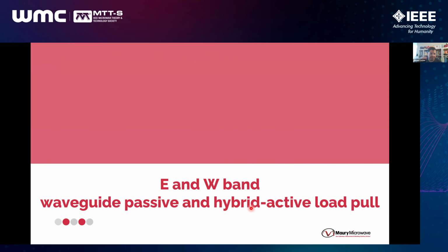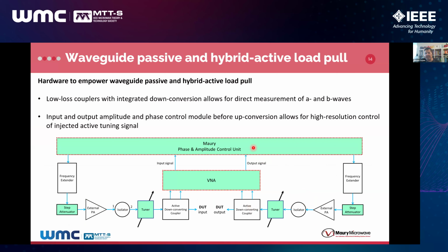And let's switch to E-band hybrid system. So in this case, we use VNA, and the critical difference here, as you know, you cannot control extenders, right? So they are kind of dummy devices. You just inject the power input signal, it multiplies, and you get the multiplied output frequency, and that's it. So you measure S parameters.